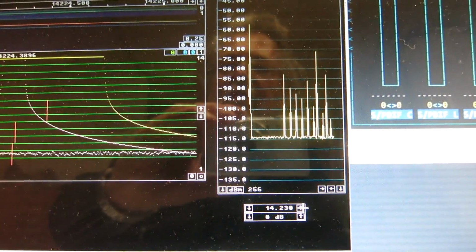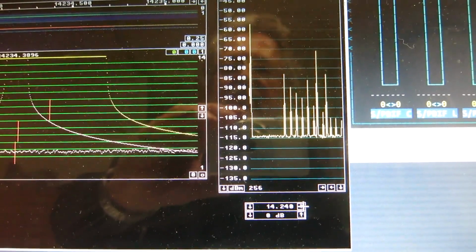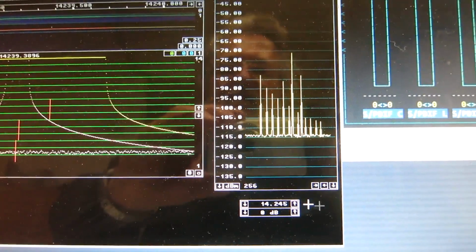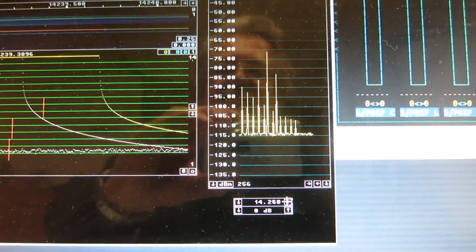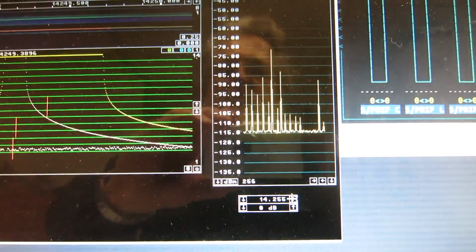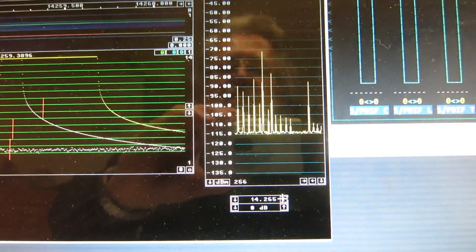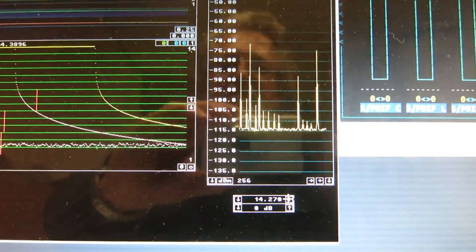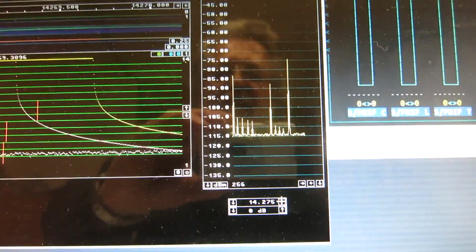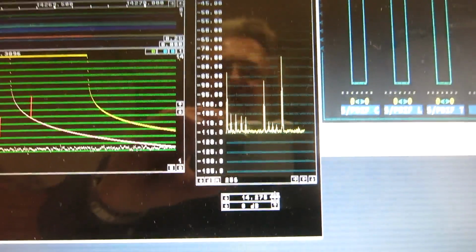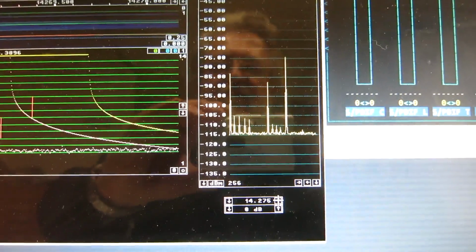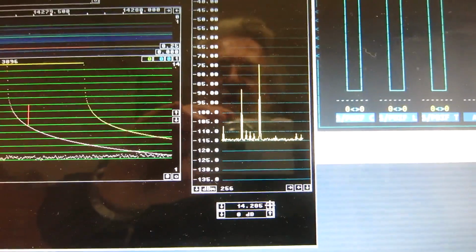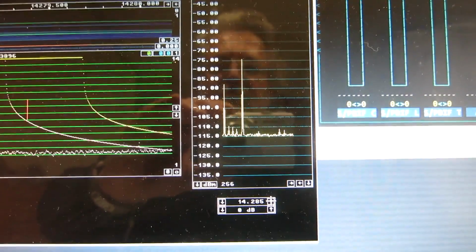And I look at the main spectrum at the same time to see if there are any noise humps or something, and I see nothing of that. Performance of this 48 kHz 16-bit card is clearly better than several of the 96 kHz 24-bit cards when I measure the dynamic range with the strong signal present.